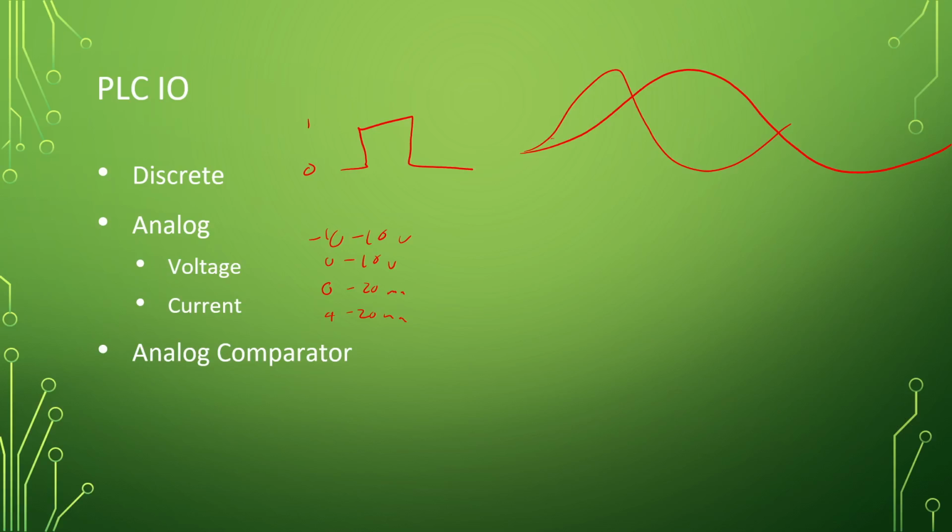Anyone have an idea? That might be part of the reason. But the reason that I know is for sensor detection. If your sensor is always outputting 4 milliamps, you know it's there, right? Whereas if the wire were to get cut, it would now say 0, and your PLC could throw a warning flag saying this sensor doesn't exist anymore.